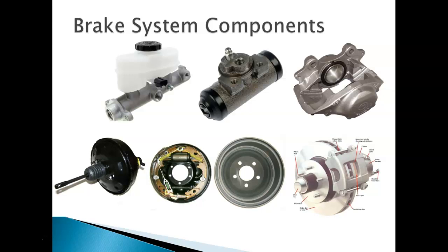So if you look right here, this is your rotor. Which, by the way, whenever you change your brakes, you're actually supposed to either change the rotor or do what? Turn it. What does turning it do? Well, eventually you get all this crud on the outside of these rotors. What it does is bring it back to true. Brings it back to level. Thank you. Okay?